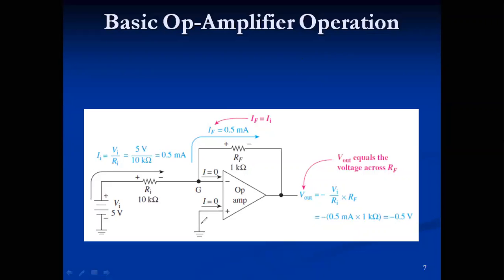Once you ground this voltage over here, and you create this feedback loop, then this OpAmp actually becomes self-regulating. And this voltage here will not vary by much. It will be a negligible variance from this voltage on the plus side. So essentially, you can say that these 2 voltages are going to be fixed. They are going to be equal to one another, because this is set to ground, so this is going to become a ground.